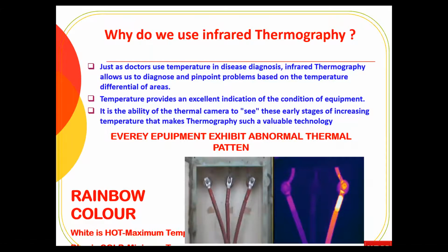When we are suffering from fever, a doctor monitors and diagnoses the temperature. According to the temperature range, he decides which kind of fever the patient is suffering from. Similarly, in the machine, whatever radiant energy is emitted from the surface is captured through the thermography camera. Then the condition monitoring thermography consultant or analyst analyzes the data taken by the thermographer and diagnoses by seeing the hotspot, hot line or hot area within the temperature scale, and by calculating the change or increase in temperature, decides what fault is happening in the machine component, externally or internally.